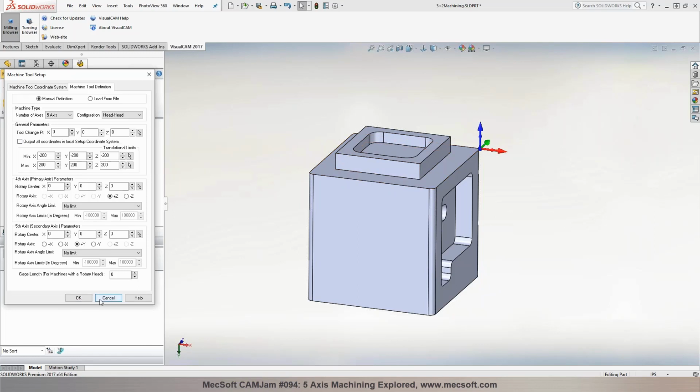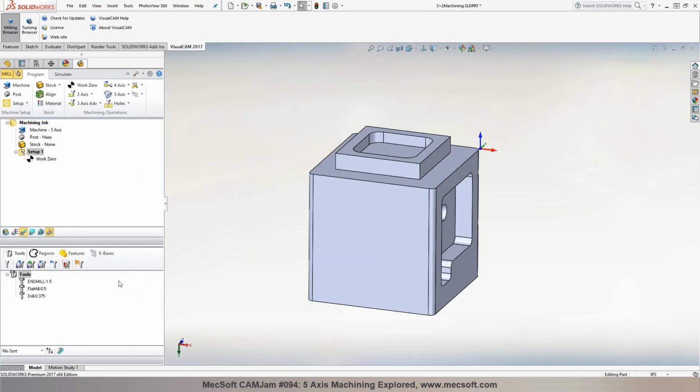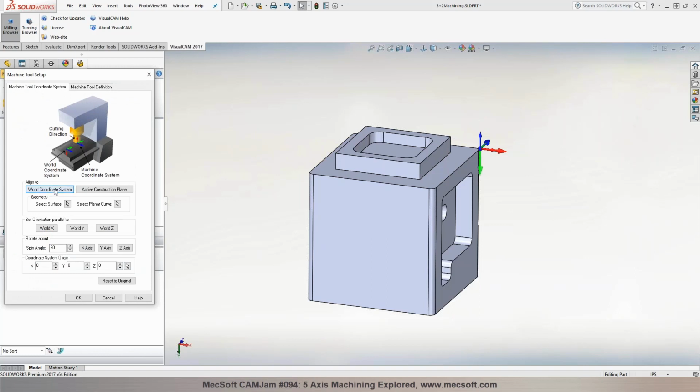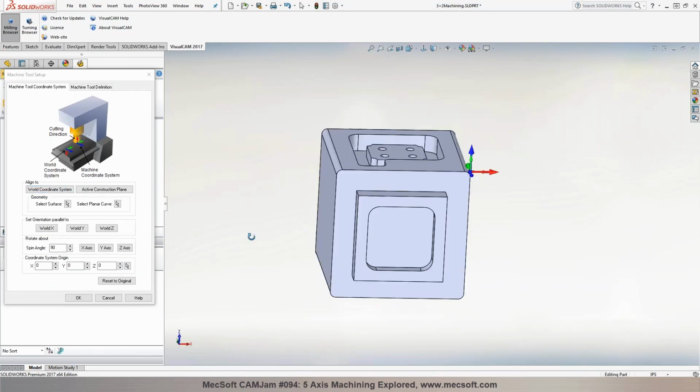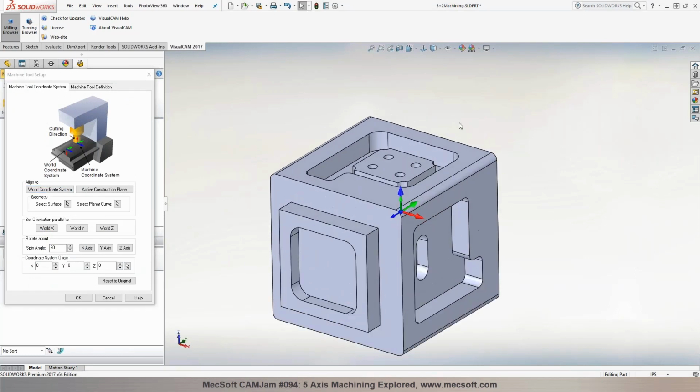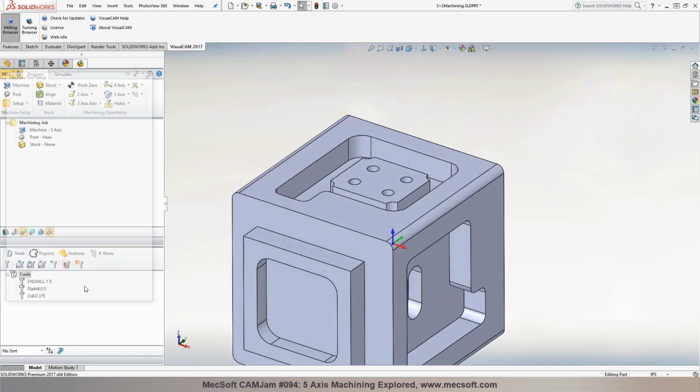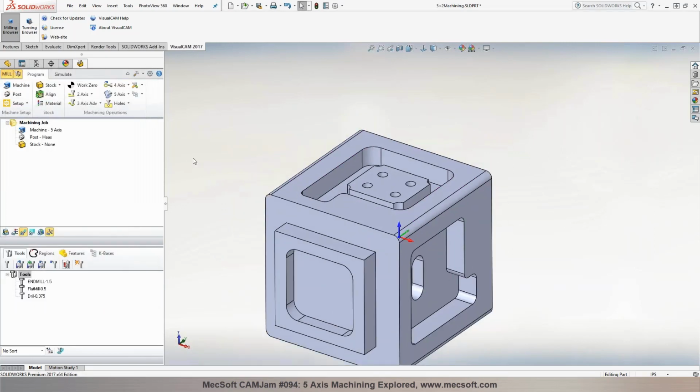So that's the reason why when you do 5-axis indexed or 5-axis simultaneous programming, you would want to establish your initial orientation, because even though you add a work zero, it'll first still go back and transform it to this position. Yeah, and that is so important, because it's so important to choose this position at the beginning of the whole process. Right, because there's only one origin that you typically reference out of when you do 5-axis programming.